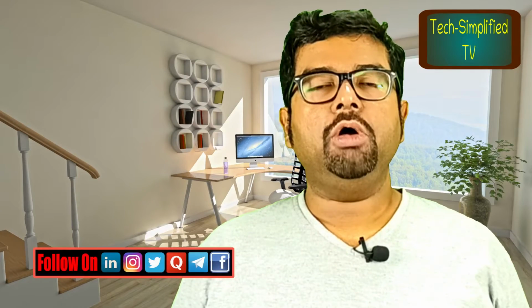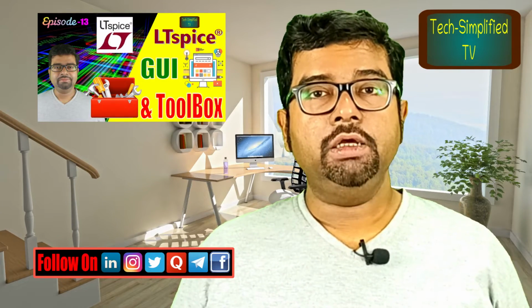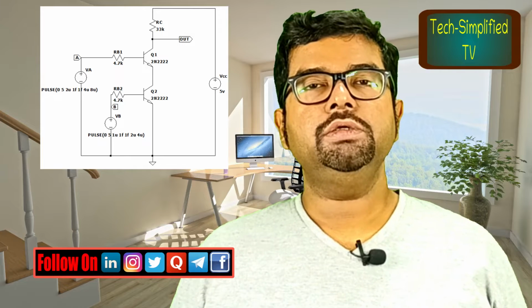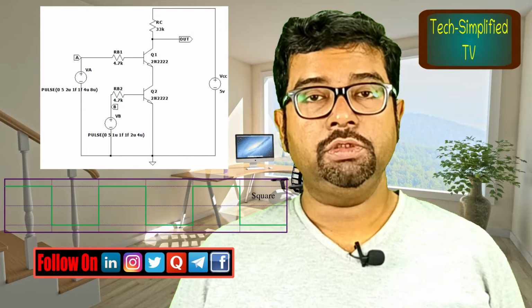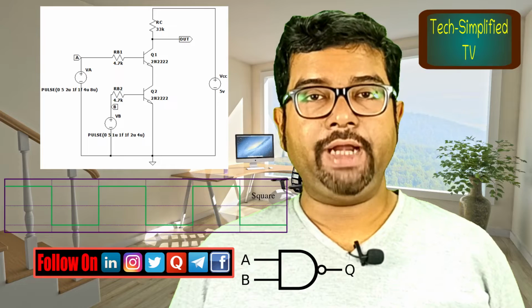Hi folks, you are already familiar with the LTSpice UI and toolbox and the basic keyboard shortcuts. In this episode, we'll construct a TTL NAND gate using two NPN bipolar junction transistors and a couple of resistors. We will apply pulsed waveforms shaped like square waveforms as the two inputs of the constructed NAND gate.